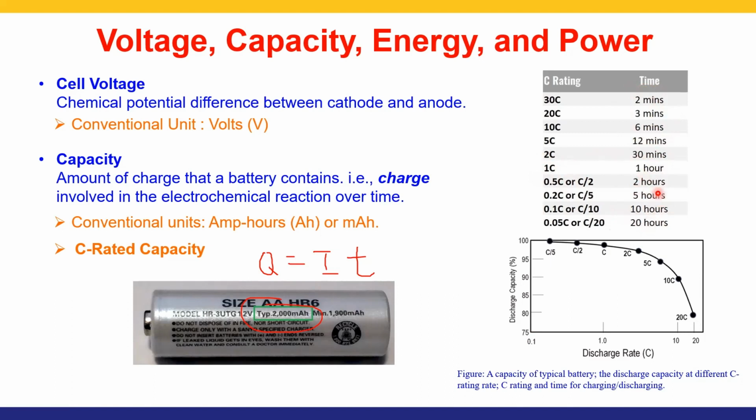However, this is just a theoretical concept. Usually we will just charge a lithium battery at 1C or less than that. Because if you charge it at a higher C, it cannot catch up kinetically and this could destroy the lithium-ion battery.